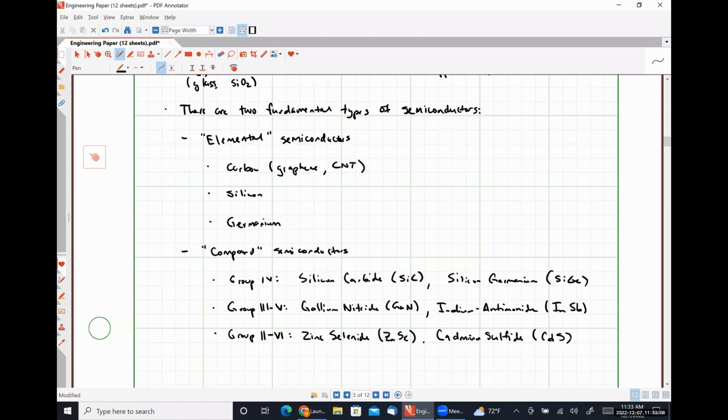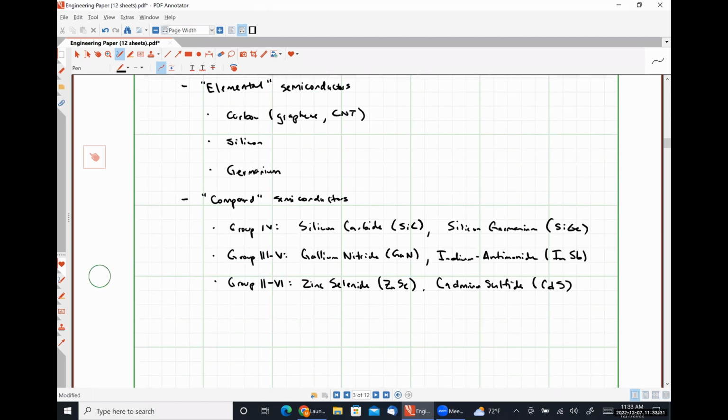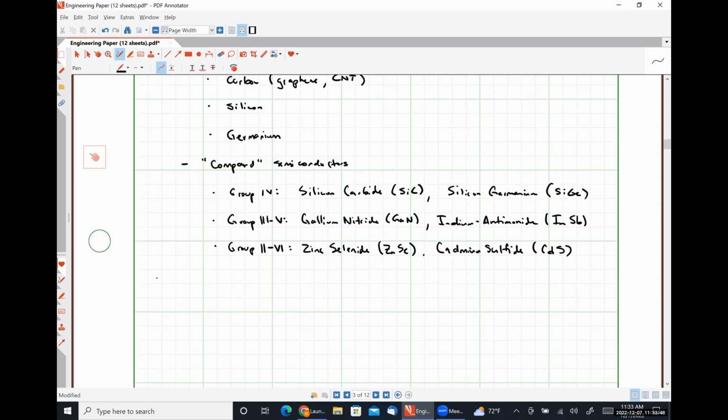There are some semiconductors that contain 3 materials, 4 materials. We have all kinds of weird, almost like ceramic semiconductor materials where the ratios of the different compounds are played with to get different characteristics. We could talk about just compound semiconductors for 3 damn days, and we wouldn't cover literally all of them, their uses and applications. So we're going to stop here because you get the gist of it. Elemental semiconductors contain a single element, compound semiconductors contain multiple elements, and the combination of the elements has some influence on the behavior of the semiconductor, both electrically and mechanically. All right. Okay, so let's circle back out here.